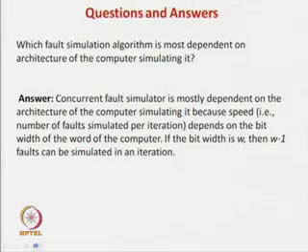But in event driven simulation, we remember whatever we have done in the previous iteration, and only for the small changes in some regions of the circuit, for a fault or for a pattern, only there we do the recomputation. So, what is the advantage, disadvantage? Obviously, event driven simulation is faster because you do not recompute anything which is redundant, but at the same time you have to remember the values from the previous iteration. So, you have to keep some extra things in memory, but the gain is speed because we are avoiding recomputation.